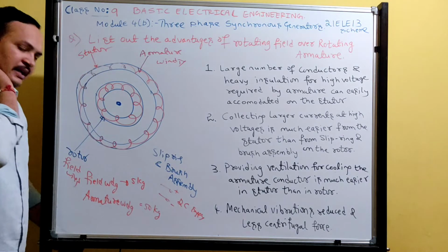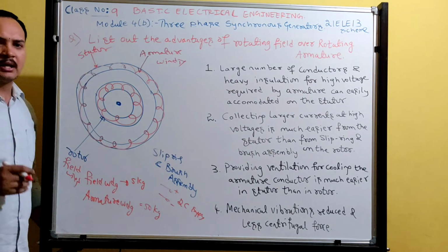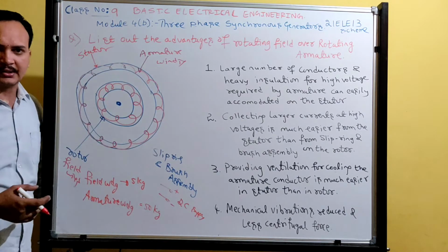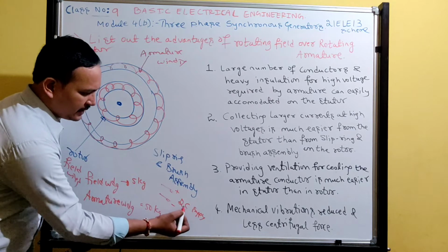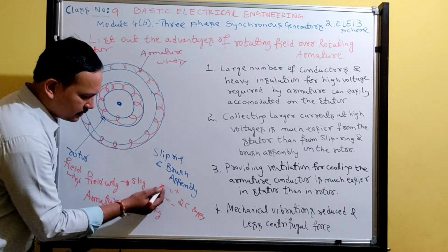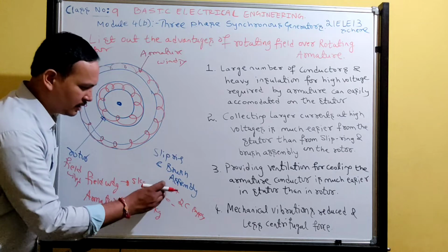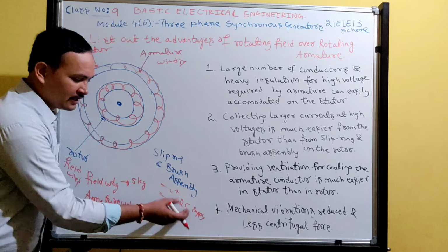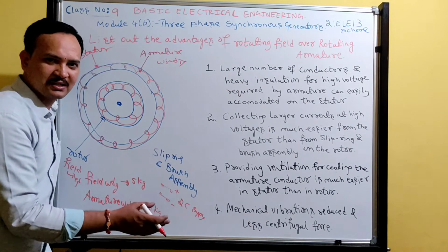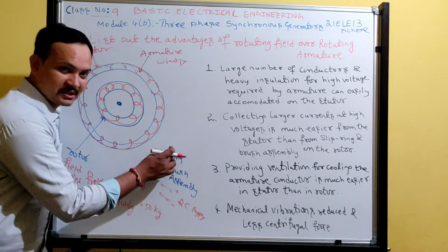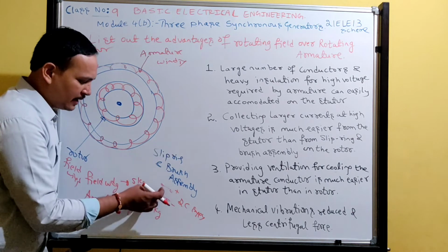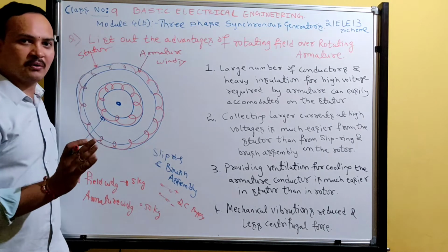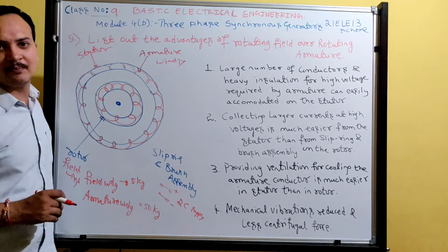Okay, you can give AC excitation also, but DC excitation will give constant rate of change of flux interaction with the stationary conductors. Okay, see, look here, DC supply is given, but this winding is placed in the rotor. This winding continuously rotates. DC supply available outside is not moving, it is stationary. So that supply is given to brushes. Brushes, and the rotating field coils are connected to the slip rings. Slip rings will rotate, brushes will not rotate. Brushes will have just contact with the slip ring.